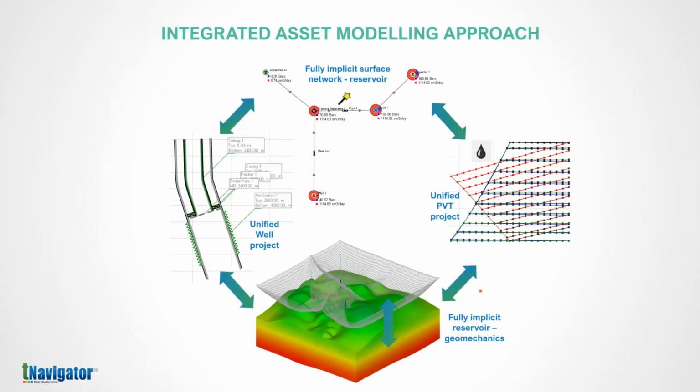So going to the integration and discussing why integration is important. First of all, CO2 is quite sensitive to pressure and temperature conditions, so we can obviously run the simulation model standalone. However, we need to understand the pressure and temperature conditions, capacity of surface facilities, and CO2 performance within the pipelines and along the wellbore. We also need to take into account the PVT properties as well. Therefore, we'll talk about all the components today.